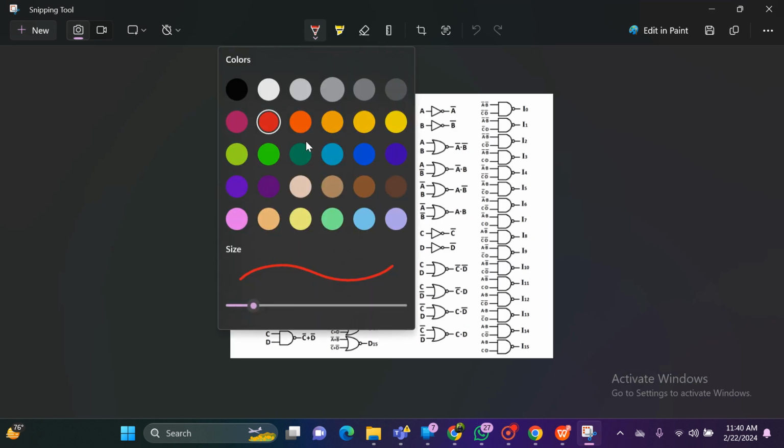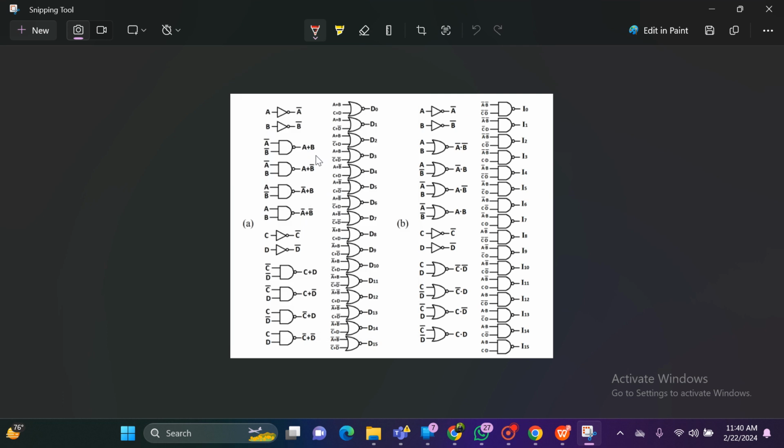So see here. So this is the NAND gate. Okay. So this is one of the 2 to 4 decoders using NAND gates. Okay. So inputs given A, B. Then next, this is another 2 to 4 decoder with NAND gates. Inputs given C, D. So here there is an input AB and here there is an input CD. So how many inputs are there? 4 inputs. Okay. Now the outputs came from these.